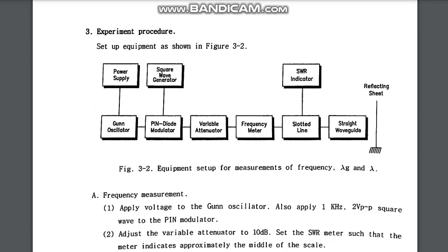Just imagine in transmission line theory, there is an incident wave and there is a reflected wave. If you know the reflected wave and the incident wave of a certain waveguide, transmission line, or microwave energy that goes through it, you can find the reflection coefficient and the transmission coefficient. And if you know the reflection coefficient, you can easily find the SWR, that means standing wave ratio.